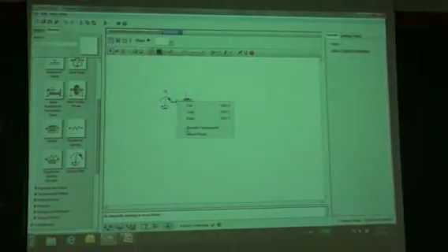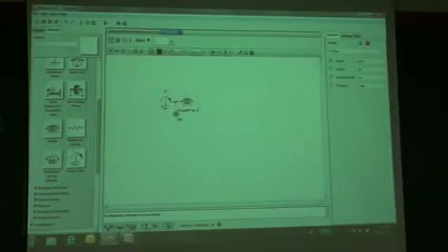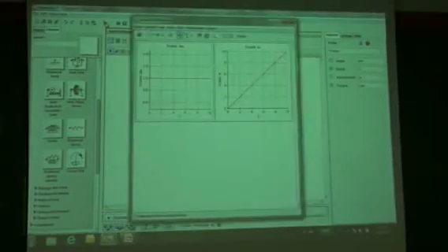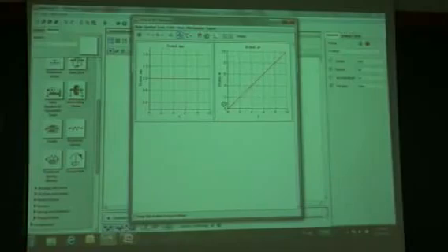Now if I click on this wire between them and select a probe, here I can see all the properties that are available. So these are all the properties that are being passed backwards and forwards between those two components. So I'm going to select speed and torque. Then run this. So we can see here we've got a static torque being applied. And because there's no resistance to the inertia, then this thing will just speed up to infinity.